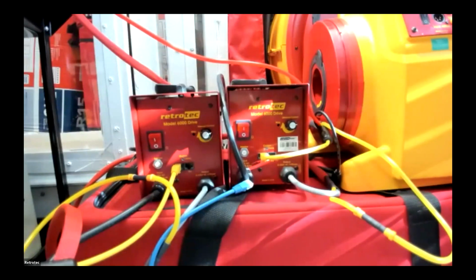Individual control is where they're all separated out. So if you have two apartments, it might take a different amount of fan power to get each one up to 50 pascals. So that's kind of the quick and dirty on how to do that. But if you're just trying to do a rough check, just to add up that CFM, you can do that.